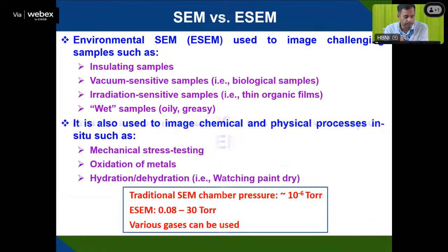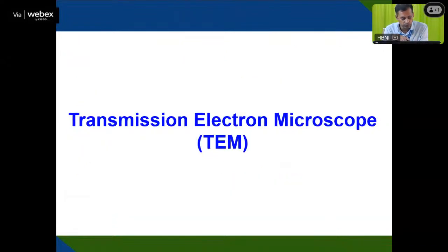So we will discuss another one, the transmission electron microscope, which is mainly useful for shape and size, to see materials in the nano range, like less than 10 nanometer, or you can see 5 to 100 nanometer. You can see the shape, size, or morphology, and you can get an electron diffraction pattern, so there you can identify the phase. So here we will take a 2-3 minute break, and then we'll discuss the transmission electron microscope.